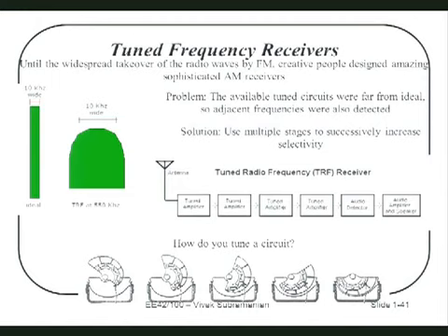I have the two plates. They're separated by a fixed distance. One way I can make a tuning circuit to tune my radio is by having two plates, and I rotate them with respect to each other. When the two plates line up, I get maximum capacitance. And when the two plates are off axis with respect to each other, I've got a low capacitance. By setting the angle, I continuously vary the capacitance. That is the knob in your old radios.